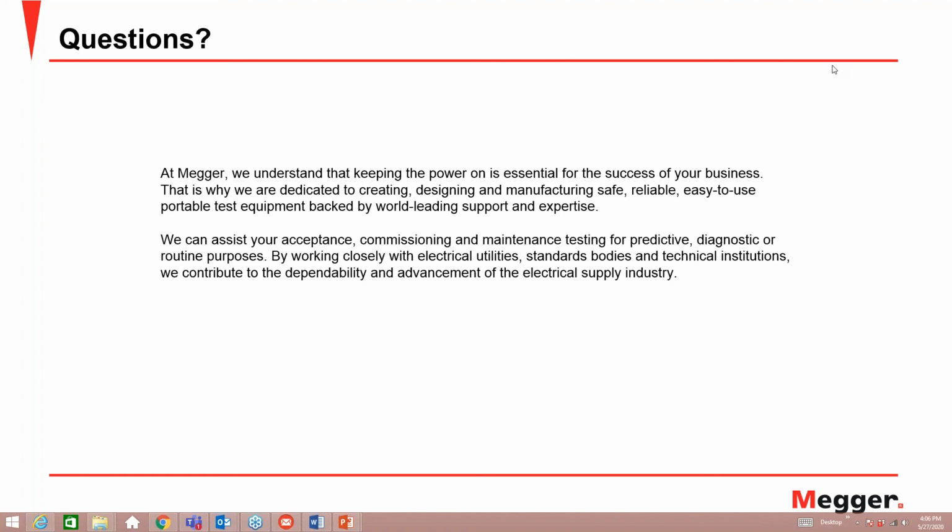Now, when we talk about batteries we're going to be using in UPS or telecom applications or things of that nature, we're really not going to be using those types of batteries. We're going to be using prismatic batteries, which have the cells in them, and those will have BMSs in them. Those BMSs are supposed to monitor and maintain the charge and discharge rates and temperatures so they don't overheat. Now, with that said, can they overheat? Yes, there's no absolute. They can, however, the BMS is a good protection for it, and different chemistries will have higher ignition points.